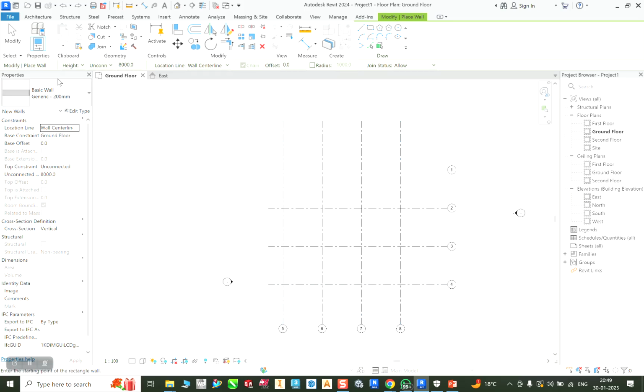Now when we are creating that wall, one thing more I want to tell you, Control Z to come back. When you select any wall, there are some parameters for that wall. These are the properties for that wall. Here you can see the depth, we are moving toward a foundation, footing side, so that we will not go into. Obviously we are going to choose height. They are going to ask up to first floor, second floor, third floor, whatever levels are there, your level 1, level 2, level 3. Now we have ground floor, first floor and second floor, up to where you want that wall. If you are going to use second, automatically it will bring that wall up to second floor.